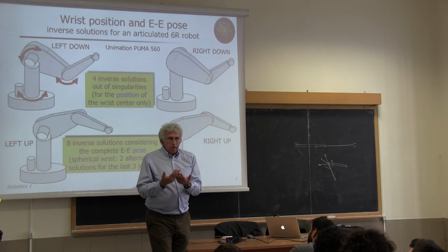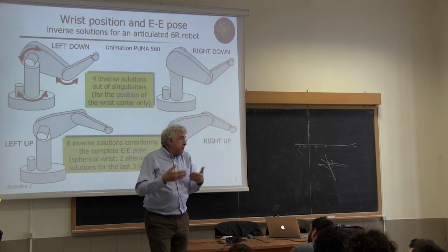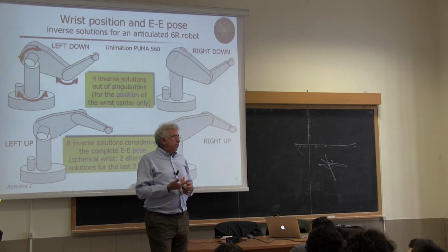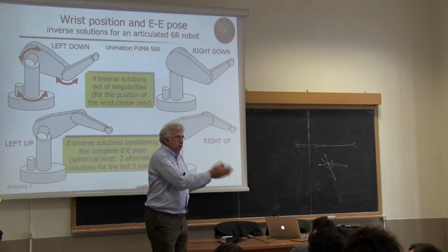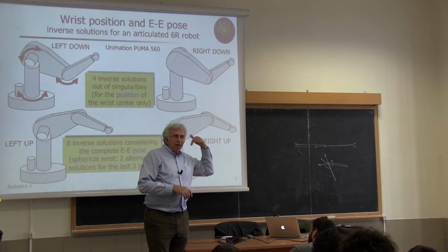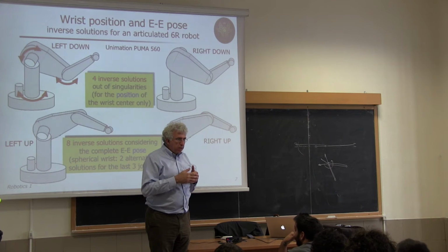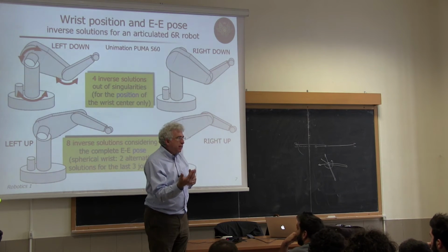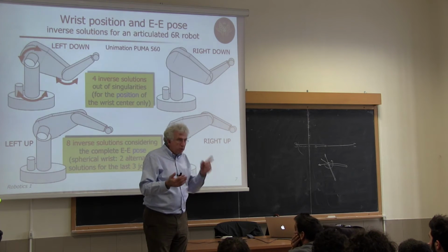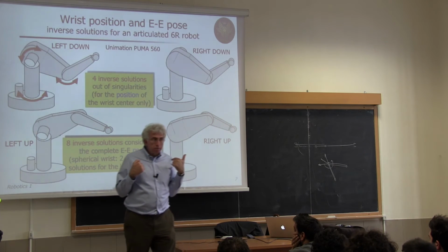Because theta 4 is the first rotation around some axis, actually a z-axis, then q5 will be a rotation around the local z-axis, but after the previous rotation, because it's an open kinematic chain. So it's an angle defined around the moving axis, because the z-axis of joint 5 has been moved by the rotation of joint 4. Okay?